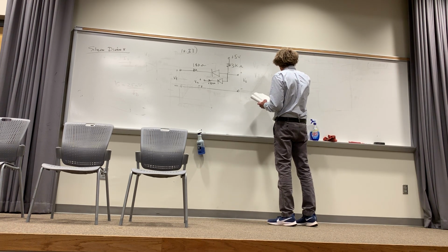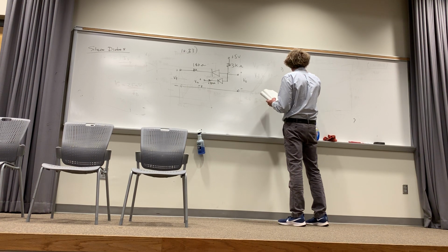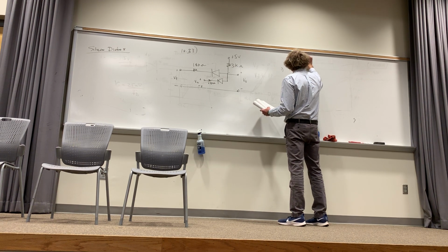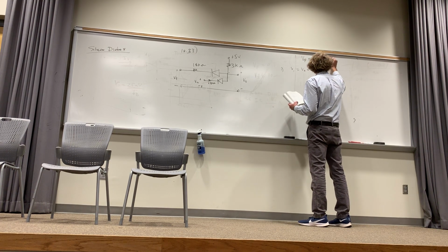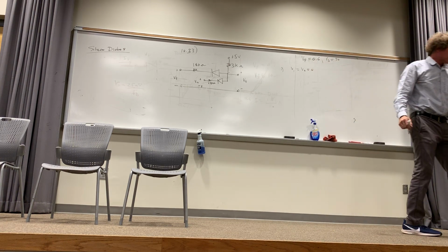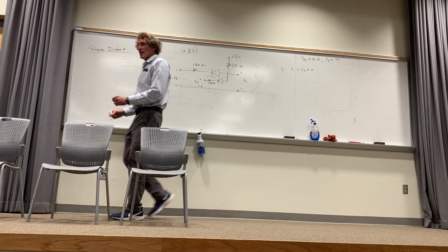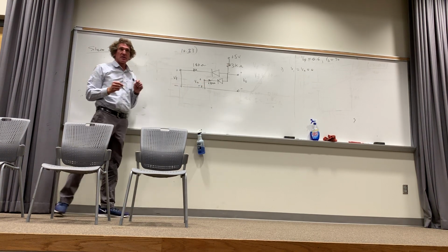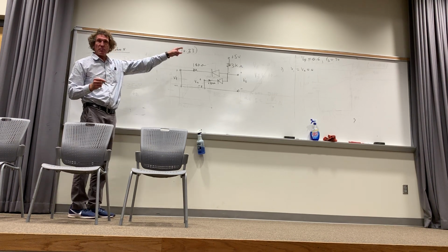this is the first part. V1 equals V2 equals 0, and I didn't say this, but the on voltage, or V forward, for this one is 0.6 volts, and RS is 30. So remember, until you get over 0.6 volts, nothing flows. So what they want to do is get the output voltage for this condition. I want you to just think about that. Those are 0 volts, right? What does 0 volts mean? Isn't that 0 volts? Isn't that 0 volts? Follow me the way I did that? Drop in the ground. Now, if that's the case, that 5 volts is between that point and ground.